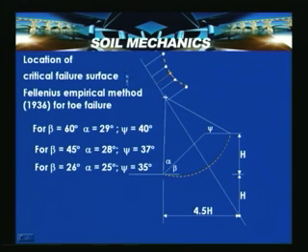So, here one can generate a grid of centers and a number of slip surfaces can be tried. One can also draw the contours which give the factor of safety, and the one which gives the lowest factor of safety is identified as the critical failure surface.